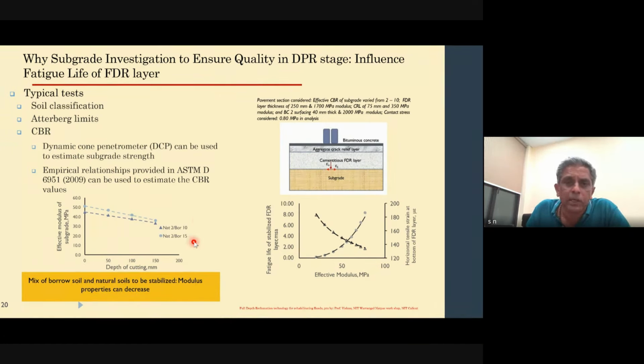Now, what happens there? If compacted, then the thickness of the bituminous layer alone, how much is that going to be? If I take a 3.75 meter wide pavement section with a thickness of 0.2, and I divide it across 5.65 meters, then instead of 20 centimeters, even if I take that layer and recompact it to 5.65, I'll end up having a layer which has a thickness of 13.3 centimeters. Not 20, it's only going to be 13.3 centimeters.